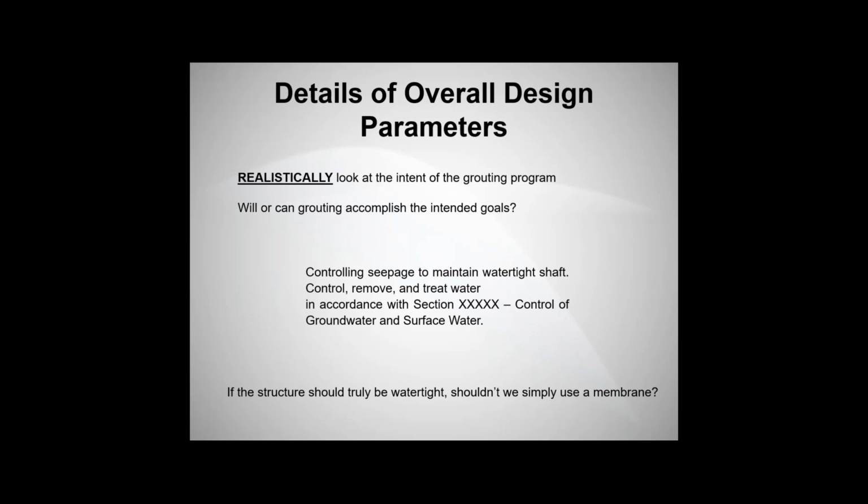But I would like to point out, I meant to say this back in the perspective section, that a lot of this reflects North American grouting practices and not necessarily other parts of the world. A lot of the grouting criteria, say in Norway, is a lot different. Whilst there are some similarities, grouting pressures, grout material, and things of that nature are different. I forgot to mention that earlier.